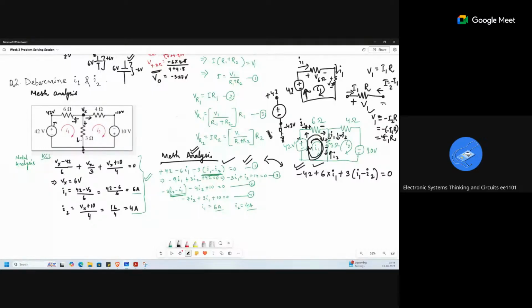So I can then connect to the ground. This end minus 42, this end plus 42 it is appearing if battery is there. If you take any battery, for example, 42 volt, and you connect your multimeter with the voltmeter, the voltmeter positive should be connected to the positive side of this battery, and voltmeter negative to the negative side.